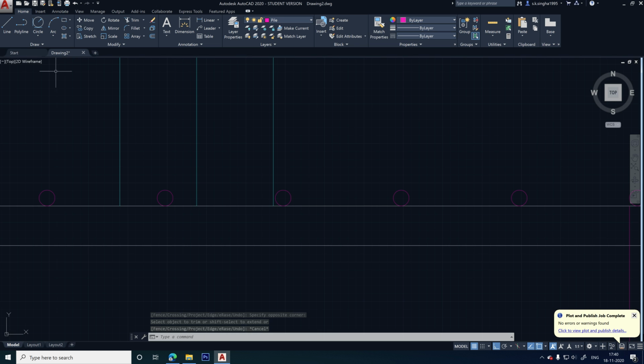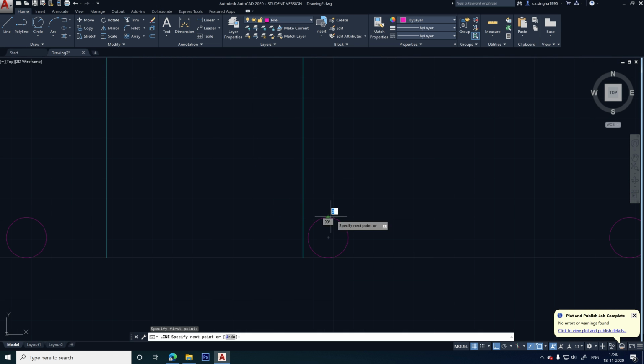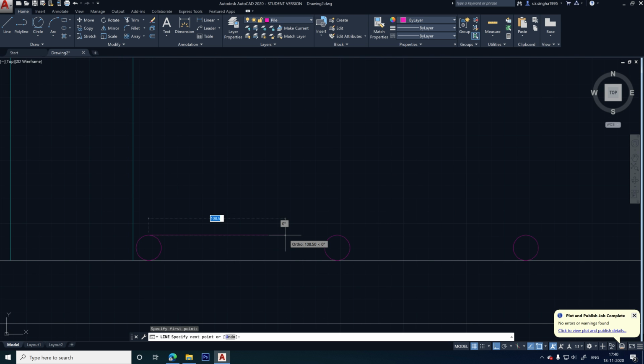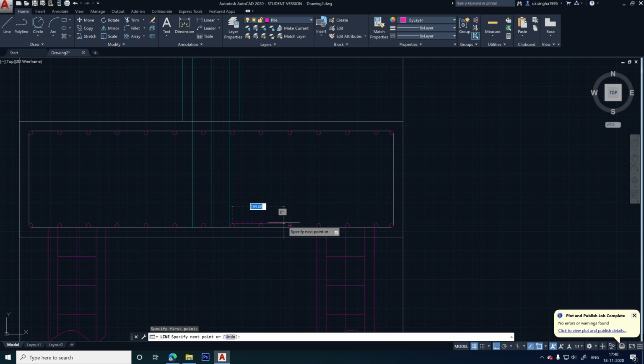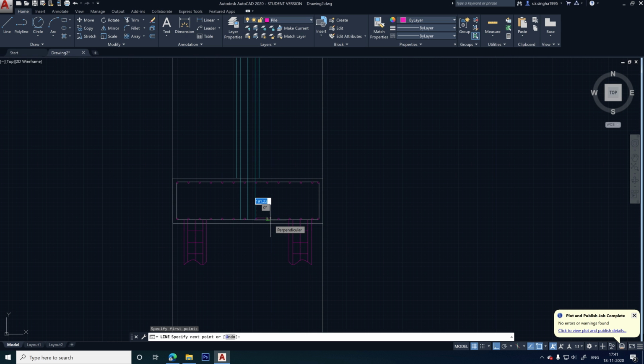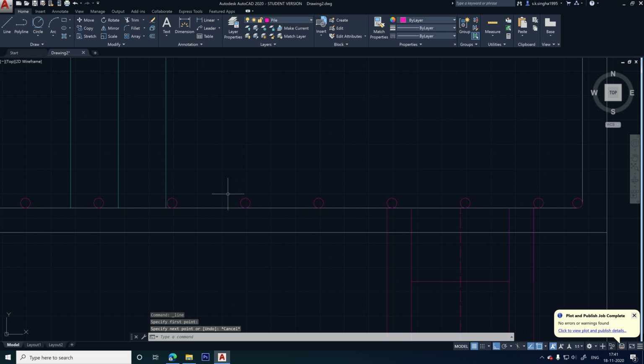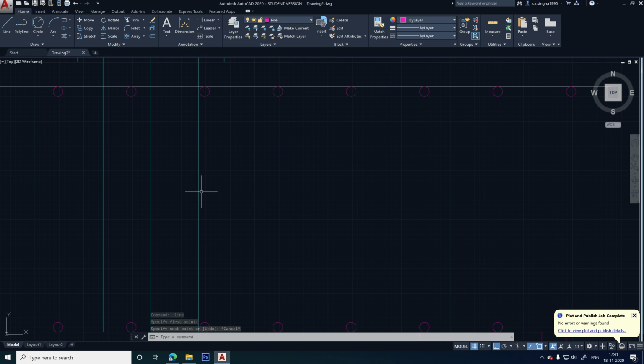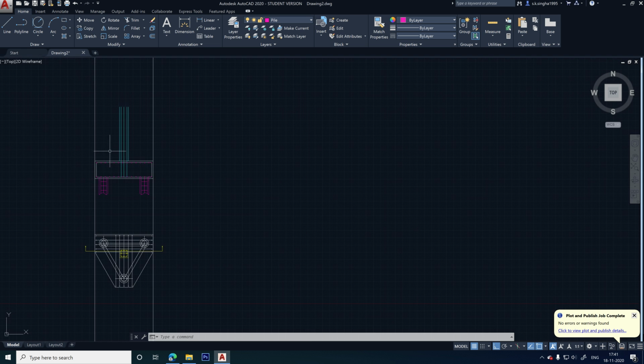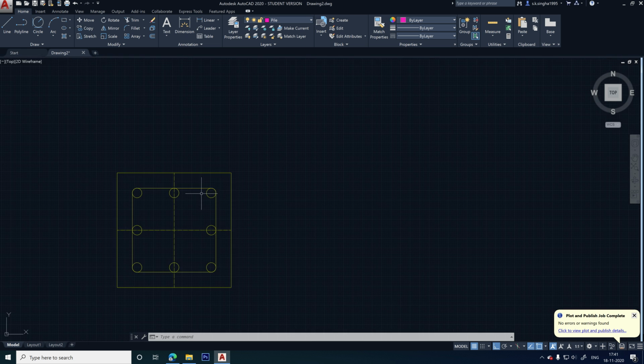Now I need to bend this, so you make a line here. It should be the reinforcement of the longitudinal column, and the distance is the development length, which should be calculated. So now I am considering it is 50D. Let us take 50D. 50D means 50 times the diameter of the bar. What is the diameter of this bar? Here we have provided the diameter of the bar. I think it is 25 mm. Let us check.